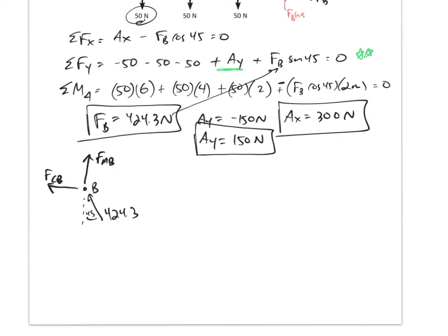All right, so for every joint, you can sum the forces in X equals 0 and sum the forces in Y equals 0. Actually, I'm not even going to do the X. I'm going to sum the forces in Y equals FAB. And the way I drew it, FAB is going up. I'm going to call X to the right positive, Y up positive.